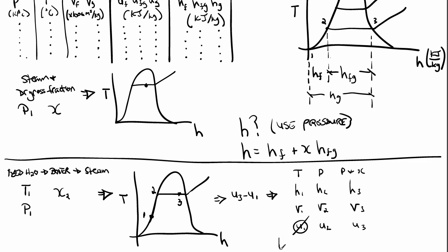What it comes down to is that formula you've seen in your books, H equals U plus PV. We'll rearrange this formula. In order to calculate the internal energy at point 1, it does need to take into account pressure, and you calculate it with this formula: U equals H1 minus PV. So we can get this, we know how. We can get this, we know how. That pressure is given.